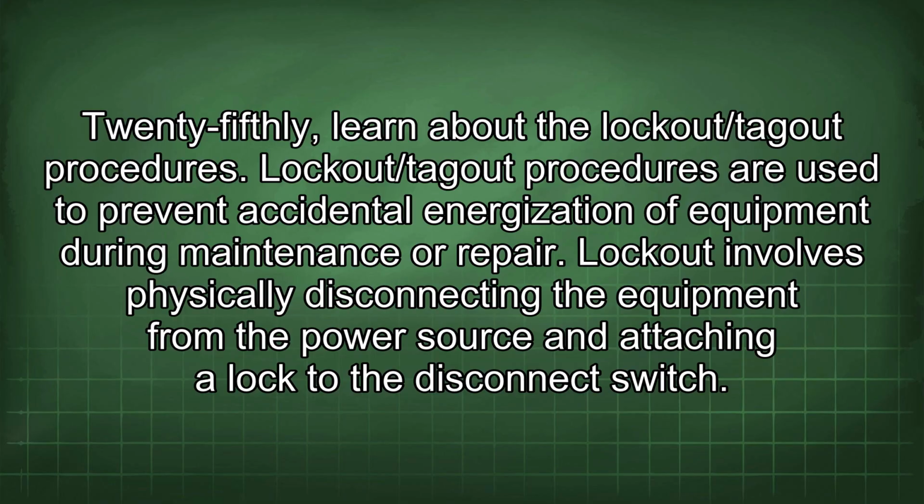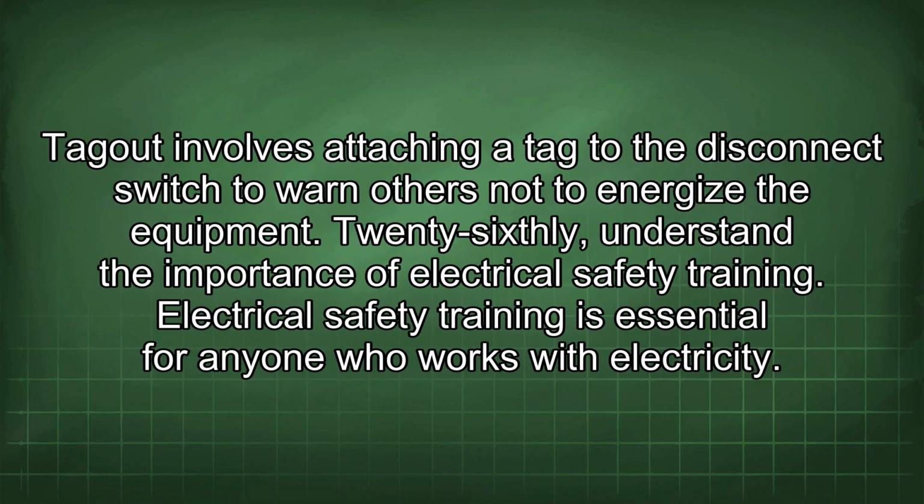Lockout/tagout procedures are used to prevent accidental energization of equipment during maintenance or repair. Lockout involves physically disconnecting the equipment from the power source and attaching a lock to the disconnect switch. Tagout involves attaching a tag to the disconnect switch to warn others not to energize the equipment.